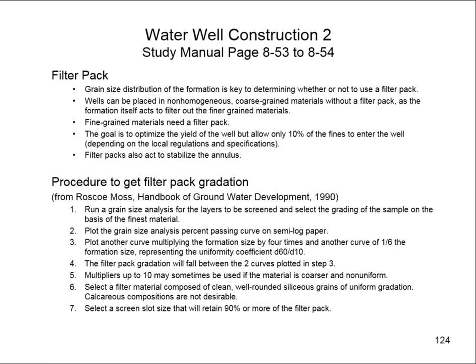And I've done that with a number of wells that I put in for a water district where we were interested in understanding the relationship between the stream and perk ponds, where they were trying to perk the water into the ground. And certain times of year when the creek had water, that could provide water into the perk ponds. But when the water wasn't flowing, the perk pond levels were higher than the creek levels, so the water could flow the other direction.